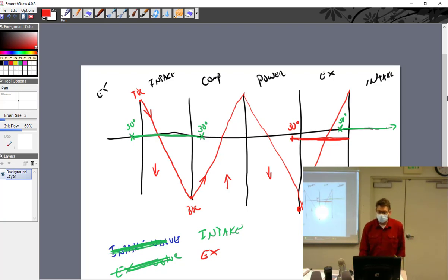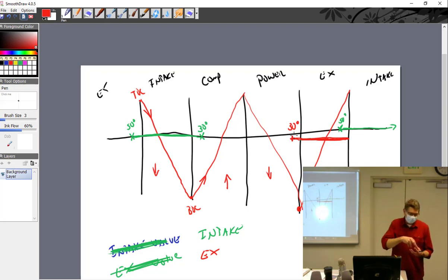Well, the reason why, and this is probably the most critical point in the whole valve timing issue, is going to be that exhaust valve. And the problem is we're talking about exhaust gases that, like I said, are in the neighborhood of 1400 degrees. It is really hotter than the exhaust valve can take, and to a large degree it's hotter than the oil can take, and there's oil around the exhaust valve stem, and that it cokes up, and we have all kinds of problems with this.